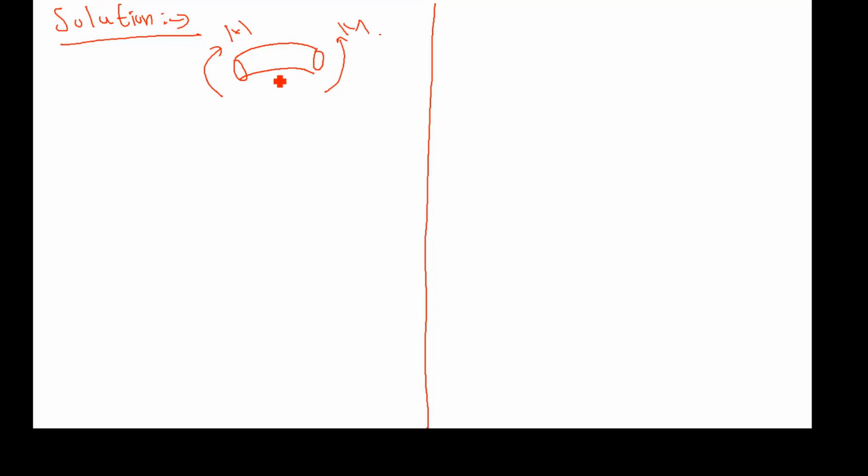So to locate the neutral axis, we have r̄ equal to A divided by the integral of dA divided by r. Here we know that the area of this bar is equal to 2 multiplied by 2 inches, which is equal to 4 square inches.